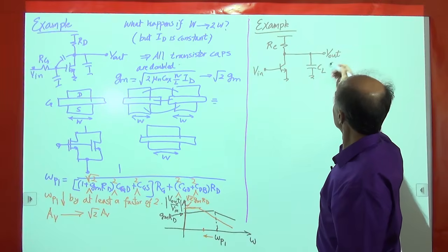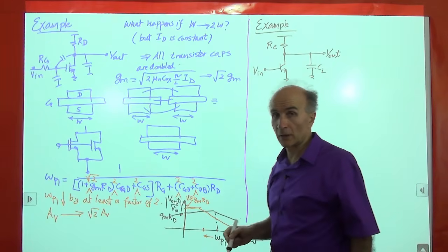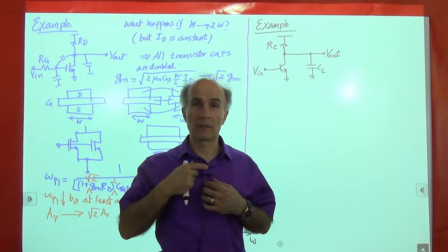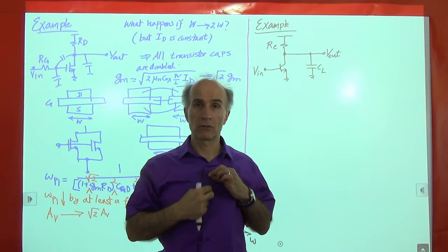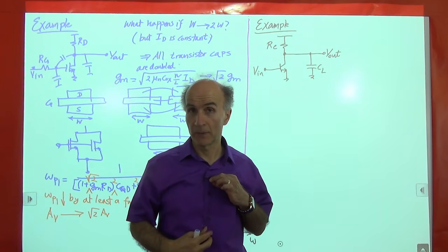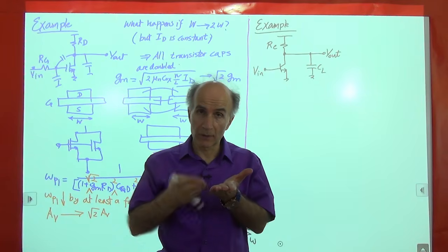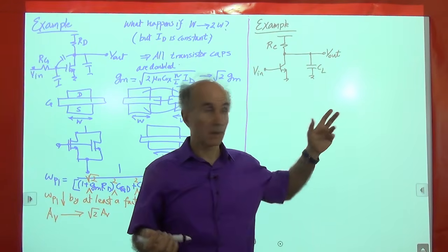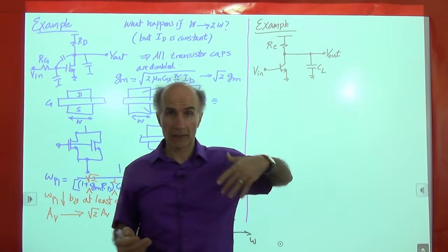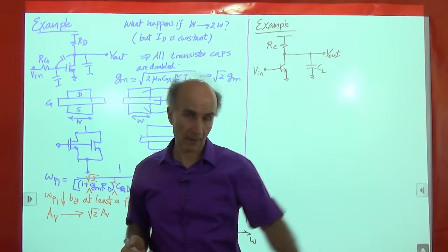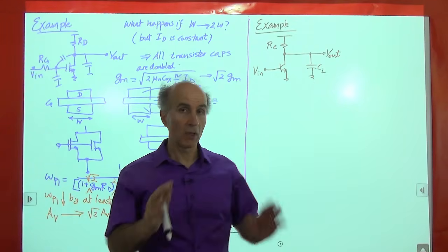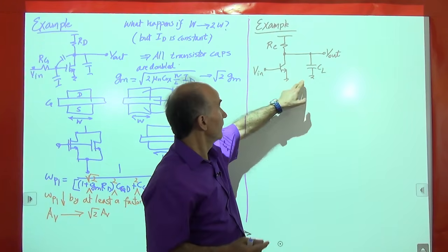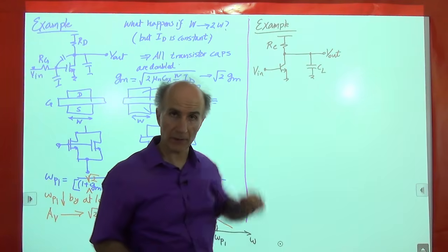Where does this come from? Well, a lot of times you have an amplifier and you have to drive a wire. So there's an amplifier in this microphone that has to drive this wire. This wire has capacitance. Or you have a trace on a printed circuit board, which has capacitance. So this is everywhere. Anytime an amplifier has to drive something, that something has capacitance. So we simplify the situation to only one capacitor, the load capacitor, and we want to study certain things.